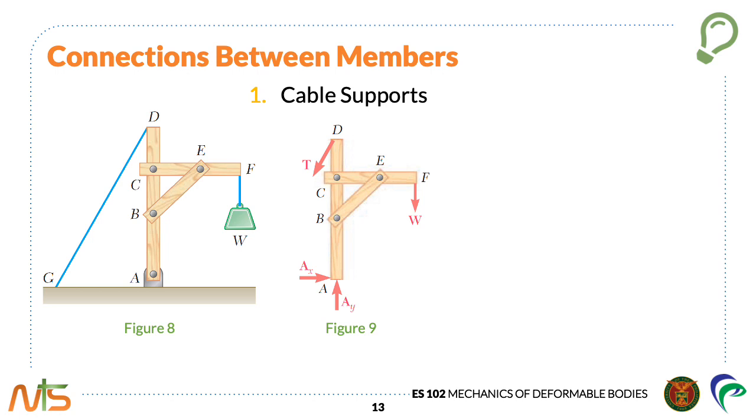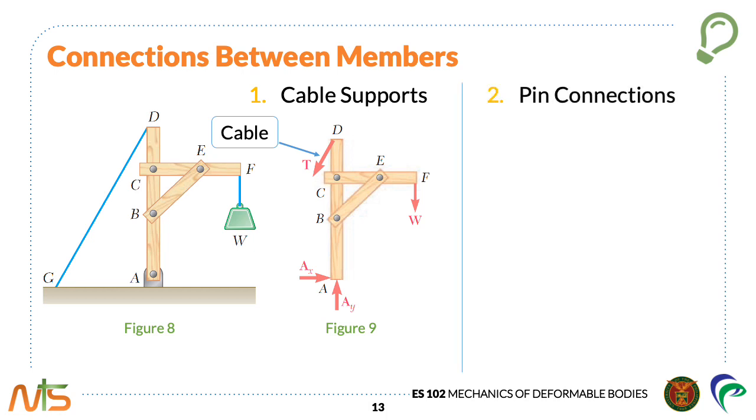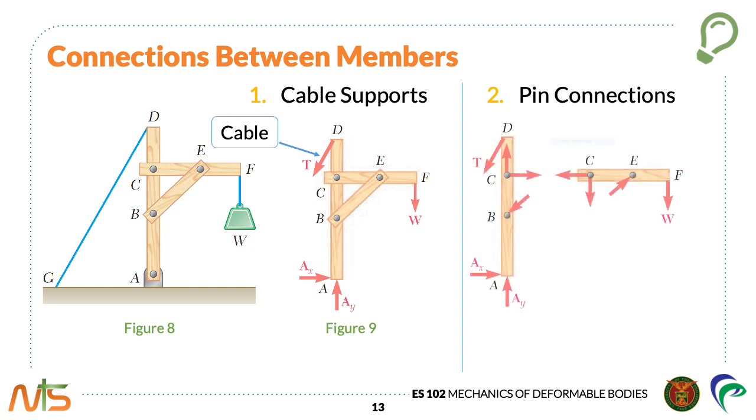The internal forces holding the various parts of the crane together do not appear in the diagram of Figure 9. If, however, the crane is dismembered, and if a free body diagram is drawn for each of its component parts, the forces holding the 3 beams together will also be represented, since these forces are external forces from the point of view of each component.